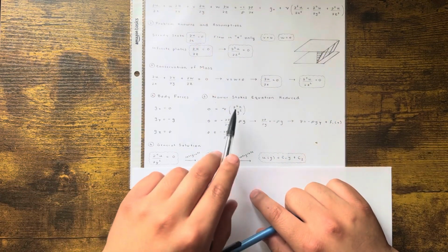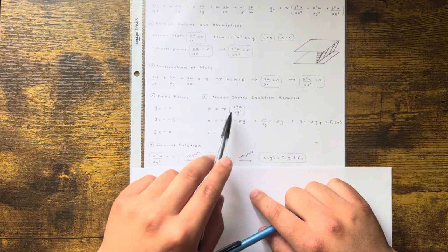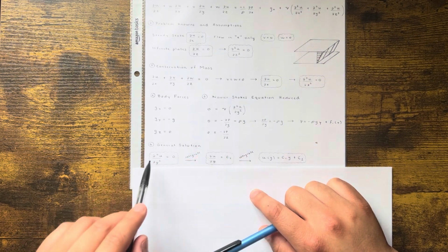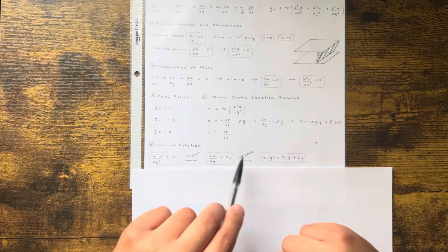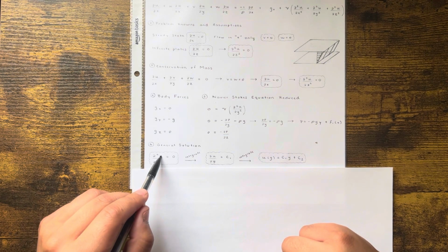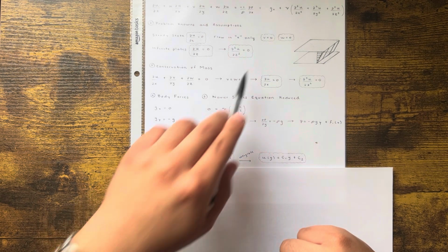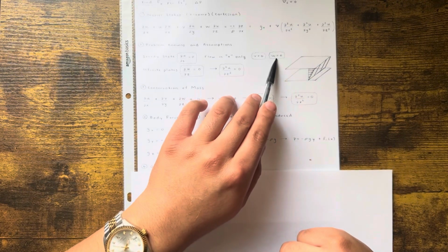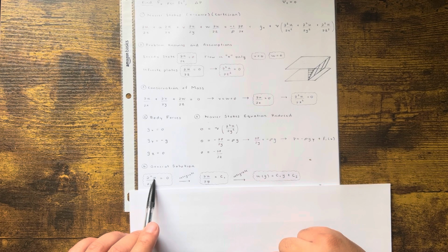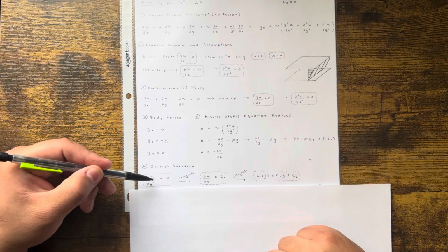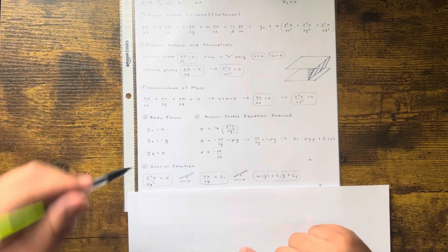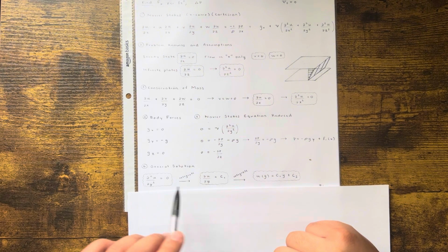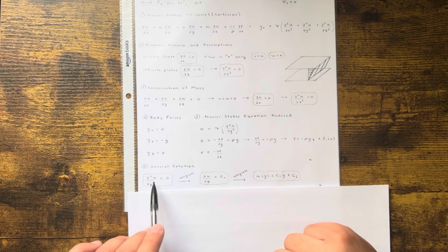So general solution. Divide kinematic viscosity to both sides, so that goes away. Now you're left with this equal to 0, which is here. Integrate it, you get that. Integrate it with respect to y, you get that. So remember, this is the velocity profile in the x direction, this is the velocity profile in the y direction, and the velocity profile in the z direction. This is the velocity profile in the x direction. How does it vary along the y direction? That's how you read these problems. How does velocity in the x vary along up and down y? Sometimes you're writing these terms and you don't know what they mean, but it's all good. You've got to start making sense of it.